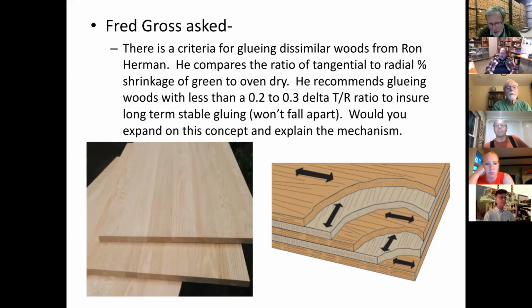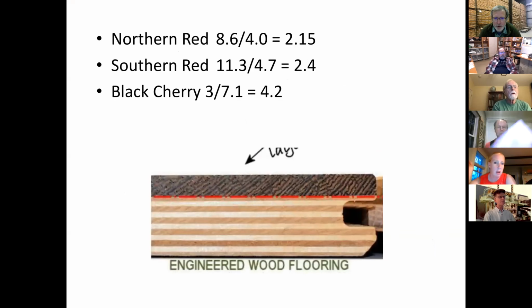I'm going to be more worried about density differences, because really highly dense woods are harder to glue. I'm going to worry more about extractive content, because woods with high extractive content are also harder to glue. However, I will agree with you in regards to the visual characterization. Yes, you can have pieces that will look funny because one will shrink and swell more than the other, which is probably why he uses that.